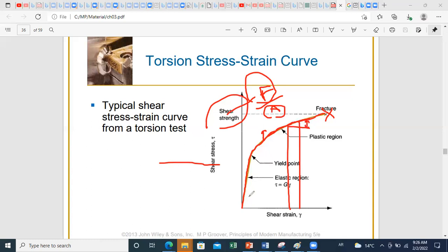While in the elastic region, for the same delta strain, you will need to increase your force much more. So it's not the force that is decreasing, but the rate of variation of the force with the strain. For a certain delta gamma, you will need a much higher delta F in the elastic region compared to the plastic region. And as you progress in the plastic region, for a certain deformation value, you will need to increase your force, but by a smaller amount. This is the idea, but your force is always increasing.